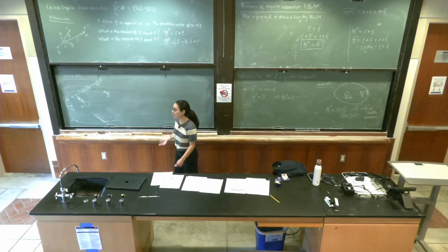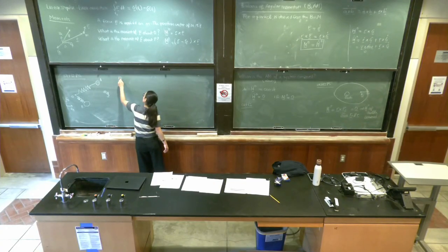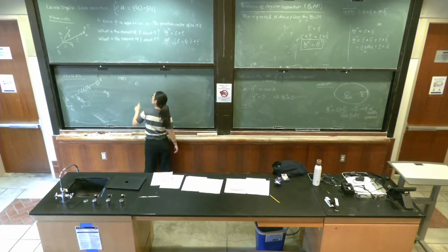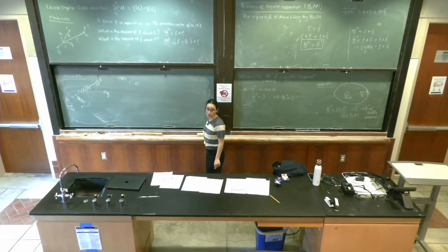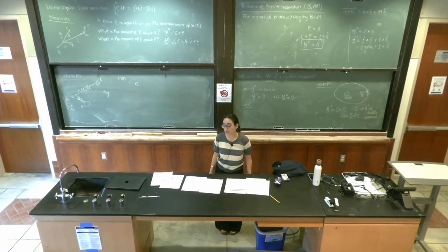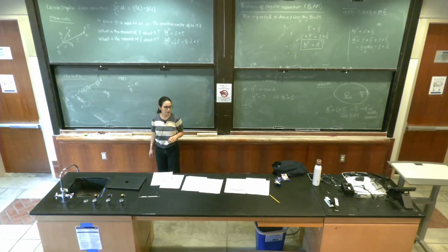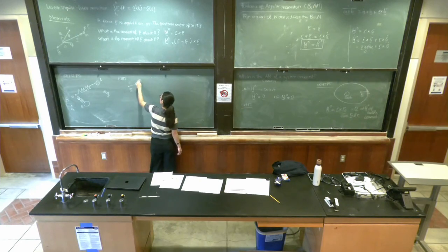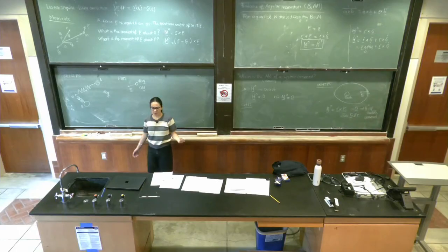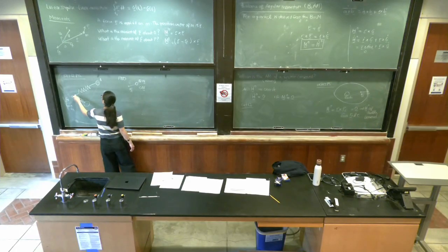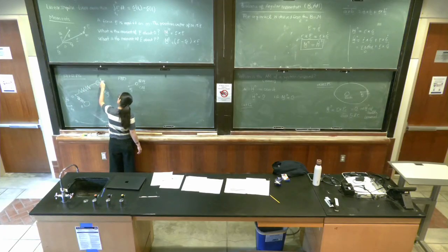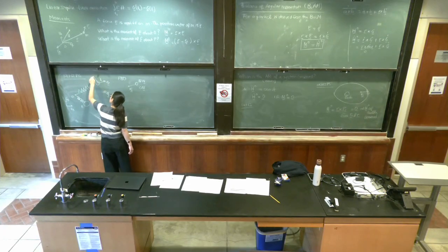If I want to draw the free body diagram of the particle during its motion, what are the forces acting on the particle during its motion? The spring force, the weight. What is the direction of the weight force? Into the page. What other forces are acting on the particle? Normal. Okay. Let me put the cylindrical polar coordinate system. This is the position vector of the particle. This is ER, and this is E theta.